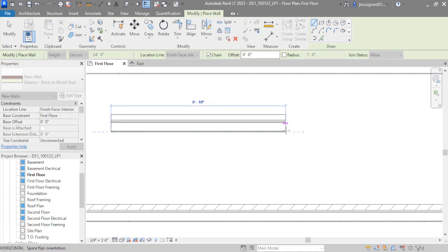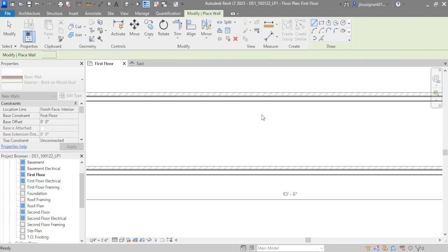And that's because that's the part of the wall that we're drawing. If I change this to core face interior, this is more acting like we're proposing a new construction. Because if you ever see core in Revit, that's pretty much your stud. You can almost synonymously connect those two. If you ever see the word core in here, or when you're dimensioning, or when something's extending into a core, which we'll go over in the future, core is stud, whether it's residential wood studs or metal studs, or commercial wood or metal studs.